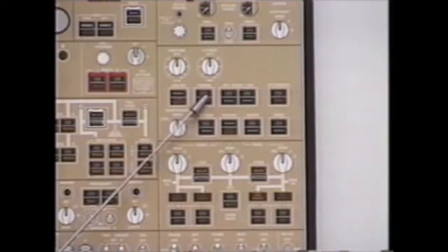Aircraft trim air uses hot air off the center manifold to mix with cool air leaving the packs to adjust compartment temperatures to selected levels. Turning off the trim air will cause all three air conditioning packs to put out a temperature that keeps the temperature of the compartment at an average of 75 degrees.